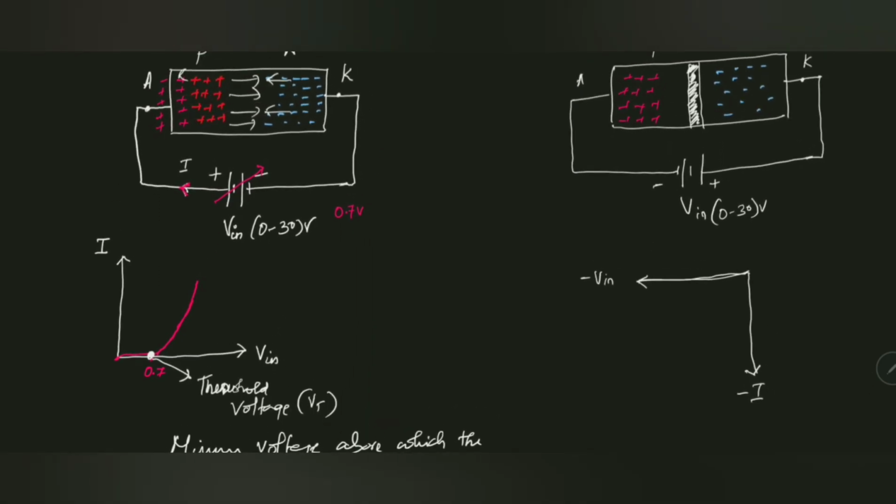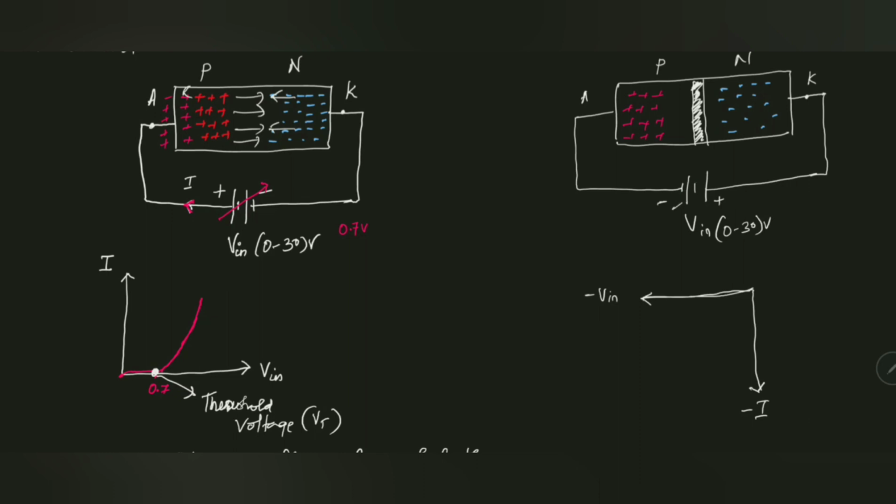So what happens exactly? When the voltage is increased from 0, since it is a negative direction, I'll keep talking about the positive value of the voltage. You should understand, since it is connected in the opposite, reverse direction, it means a minus voltage. As I increase it, the negative part, which is connected to the anode, makes this p-type gain some electrons. So electrons get accumulated, it still gains electrons here, and similarly here it gains positive charges.